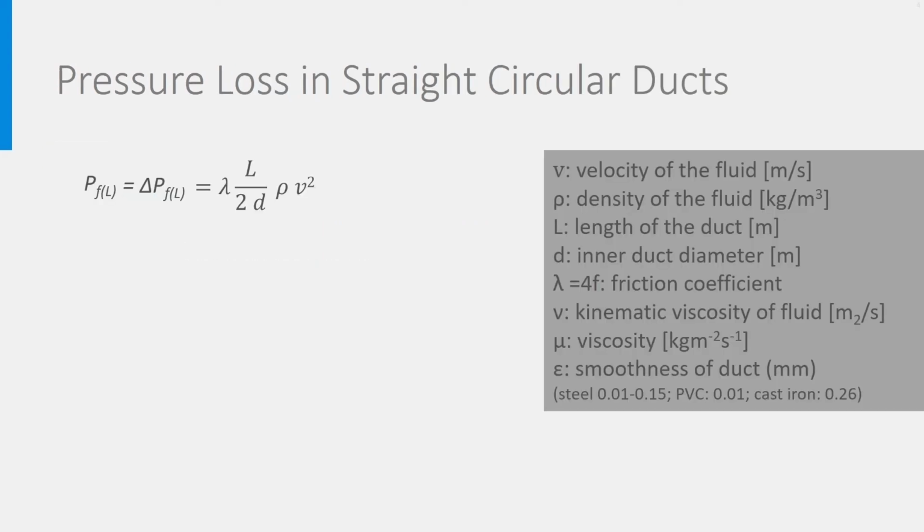We just described it extensively. When a fluid flows in a duct, friction pressure is unavoidable. It is good usage to call this friction pressure pressure loss, as we have to compensate for it with a pump or a fan to ensure a constant fluid velocity and a constant volume flow rate. They are generally referred to as delta P.